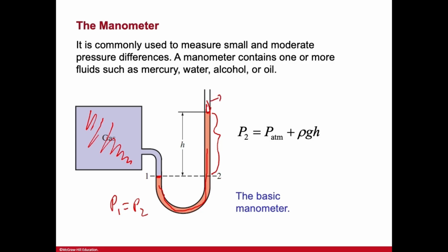It is open to the air on top, so essentially the pressure on this face would be atmospheric pressure. If I draw this section, you have atmospheric pressure on the top pushing down, you have P1 pressure or P2, however you want to say it, P1 equal to P2 pushing up, and then you have the weight of this liquid column pushing down, right?